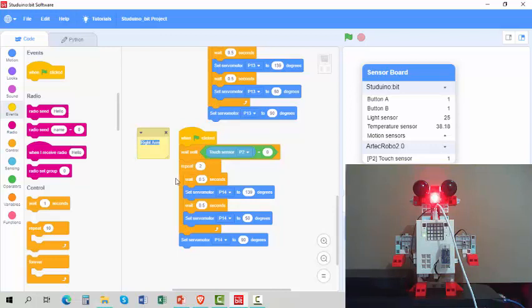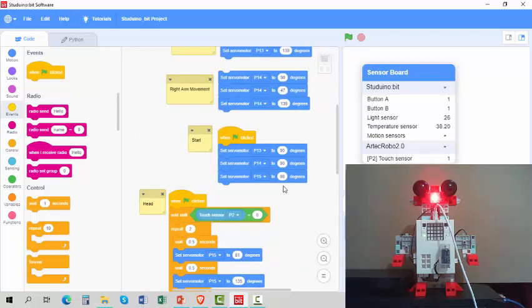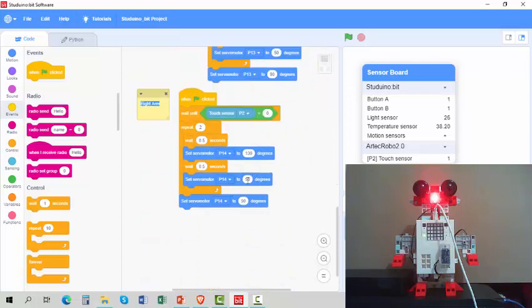So again, when touch sensor work, we repeat this twice just to test it, left arm, right arm, and we get our parameters for the right arm, 47 and 139. I think we set it the same. 47, we can have it like that. I think that will work just fine. So let's test this, and I press the button again. Let's look at the arm. It's moving just fine. Great. So we've got that part going also, and now we are pretty happy with the arm movements.